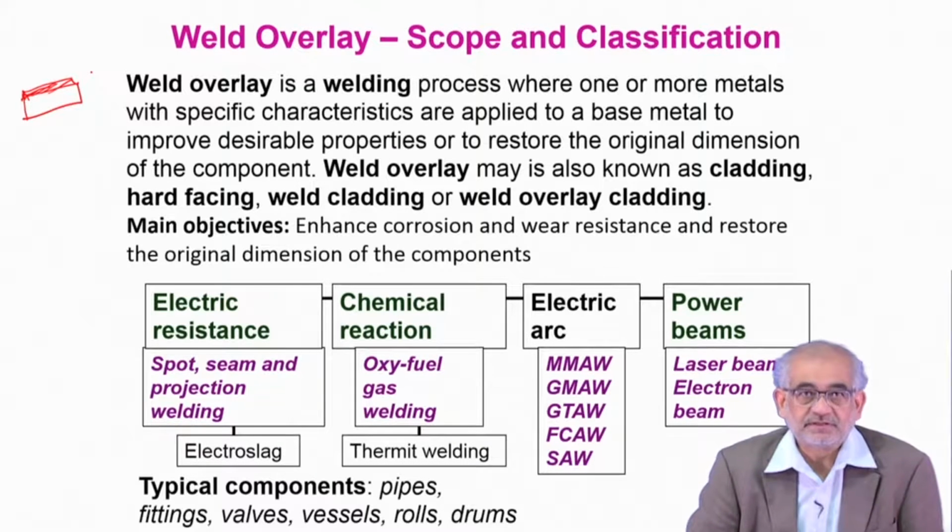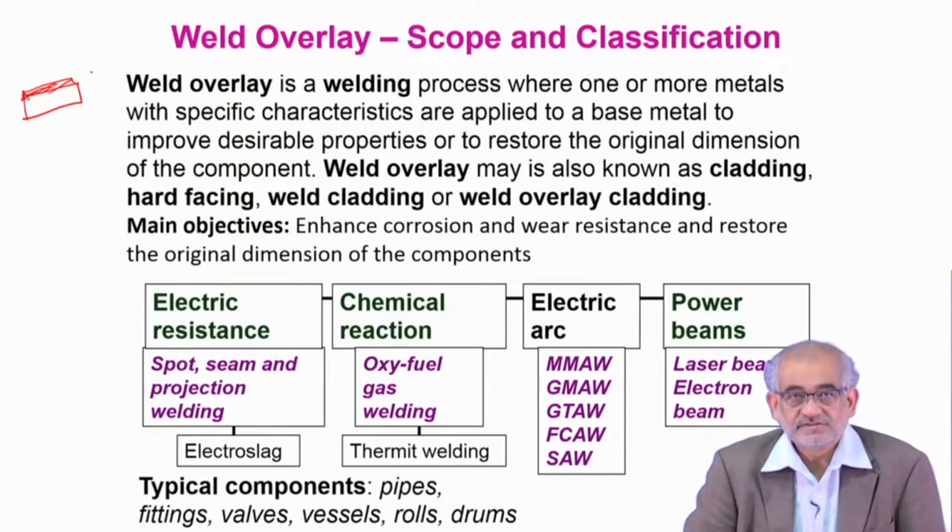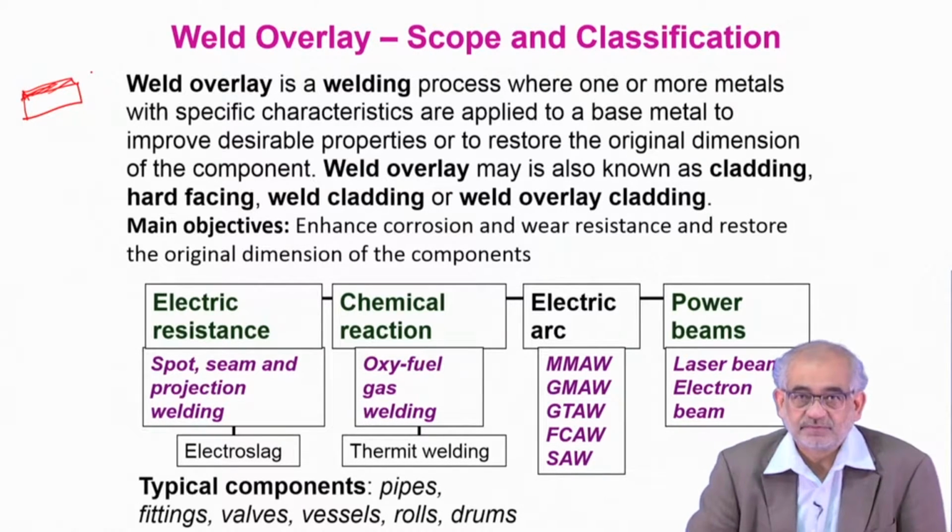So, we are not dependent on solid solubility, nor the diffusion coefficient. So, the thermodynamic or kinetic barriers do not play much of a role here. What is very important is that we should have a reasonable amount of interfacial bonding adherence. There should not be any big mismatch or spoliation, and the coating also can be fairly thick.